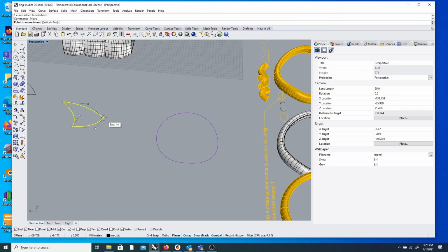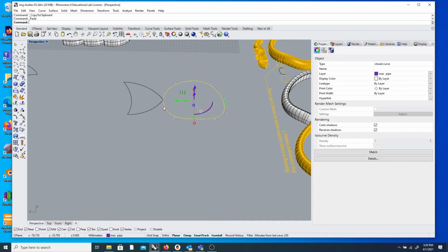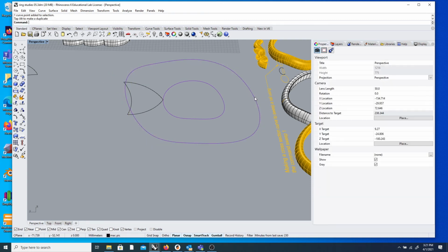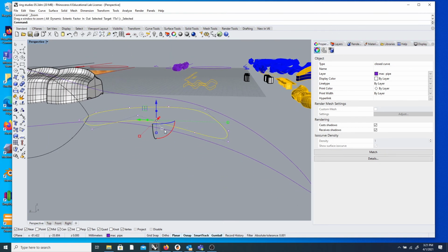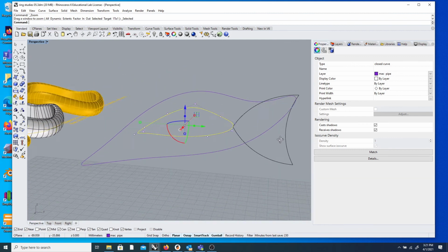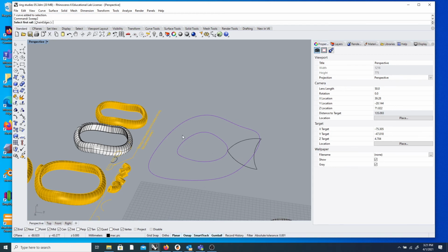Move it to quad, and then it's going to be weird looking. Oh, it's going to get better. I'm going to use 2 rails. Oh, okay. So we'll manipulate this a little bit more. So in space, I've got my center rail, and then I've got my external rail, and I've got my cross section. So if I go sweep 2, select first rail, second rail, cross section, enter.